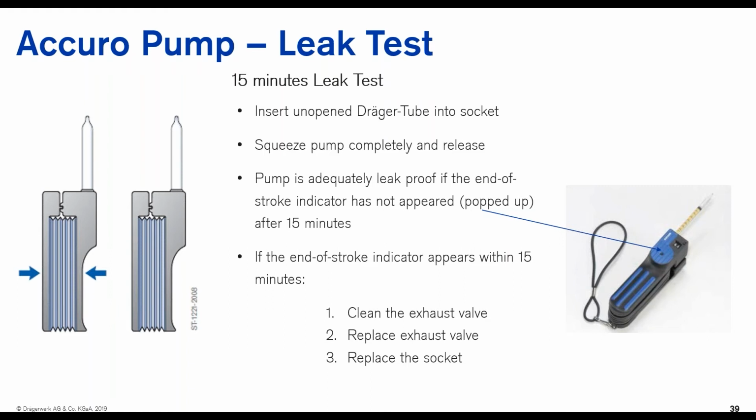First, you need to insert an unopened Dräger tube into the socket, squeeze the pump completely and release. When the pump is leak proof, the end of stroke indicator will not appear after 15 minutes. If the end of stroke indicator appears within 15 minutes, there is some maintenance you need to do, for example, cleaning the exhaust valve in the pump itself, or replacing the exhaust valve.